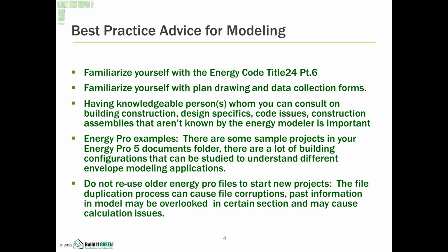And it's always a good idea to not reuse your old energy profiles as templates. I've seen that file duplication causes some errors and file corruptions, and past information always gets overlooked, and it causes certain loads, depending on if it's in a fan or heating or cooling or windows. I've seen it give calculation errors and cause buildings to not comply. So if you start from scratch, with a new file, it's always better, and just give yourself time to build out a full model.